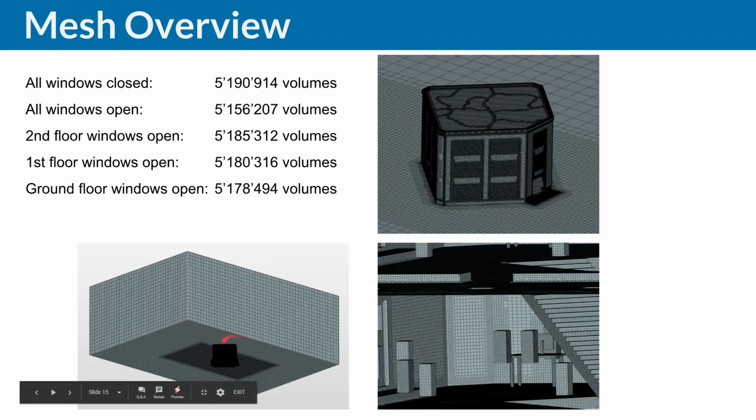The rule is that you need to make the mesh fine wherever you're interested in the result and wherever you expect high gradients and high changes. This kind of refinement is done automatically. We have refined the edges because there we will have a lot of interaction between the flow and the building, and you can also see inside the building where we increased the resolution for small objects.